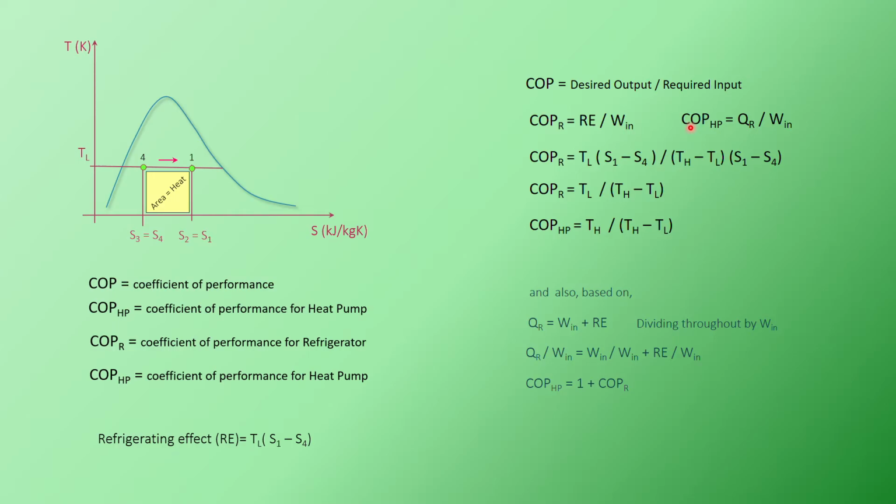Now, on the same cycle, you can also look into something which we call a heat pump. That is the condenser part. That means you are ejecting or discharging heat, or supplying heat energy to an environment, especially in colder countries. Okay, you require a heat pump. So if you revert or convert a refrigerator, you will actually get a heat pump. So a heat pump is where your condenser is.